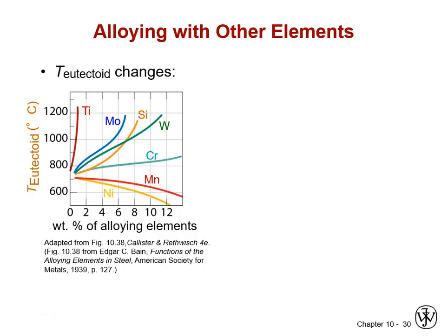Even what we call plain carbon steels tend to have a few other alloying additions just to manage impurities and allow for processability. We do put other alloying additions in specifically to drive hardenability, toughness, corrosion resistance, etc., without ever encroaching on the realm of, say, stainless steels or ferrochromes or high nickel. These are what we call low alloy steels, where we'll put any one of these elements shown here on this diagram in specifically to alter properties, usually mechanical properties. And these will be present in somewhere less than 5 weight%, quite often less than 1.